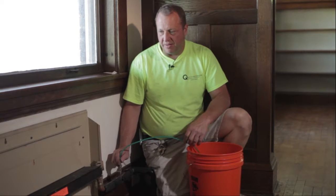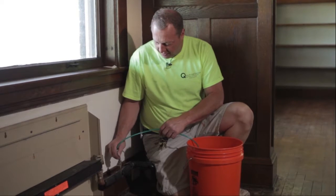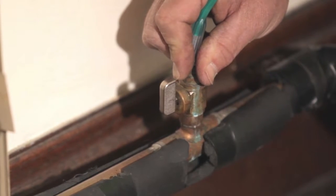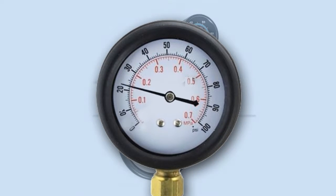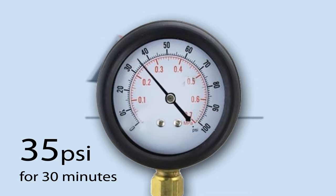For best practices, use a small hose or tube to blow the lines into a bucket. When blowing out the lines, remove the bleed elbow and pin from the pipe to ensure an airtight fit. Once all water has been blown from all lines, a pressure test is required to ensure the system holds the pressure and has no leaks. The pressure test should be done at 35 psi for 30 minutes.